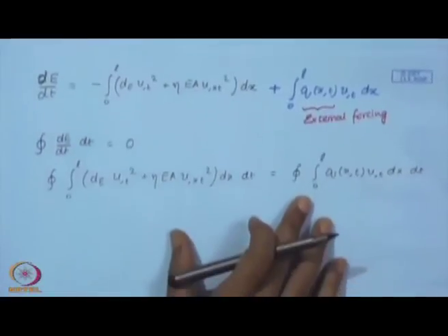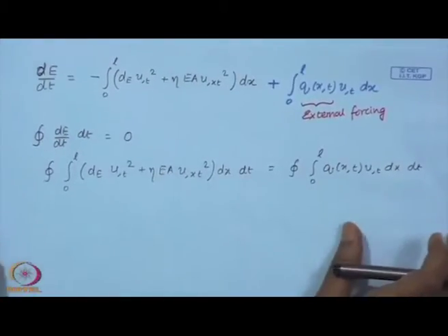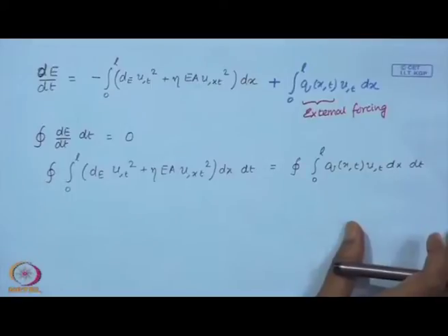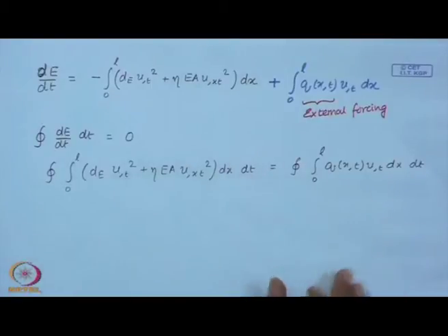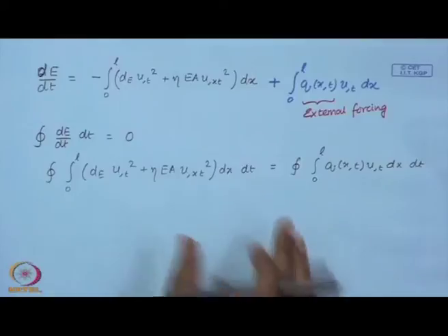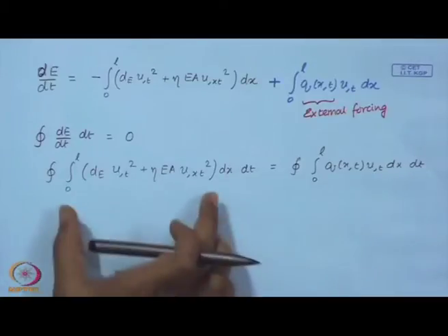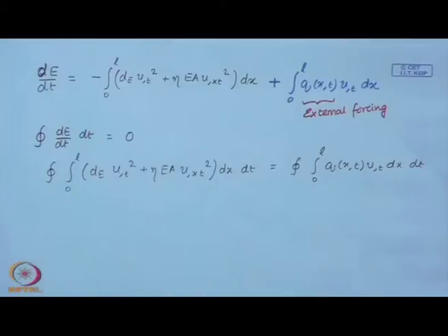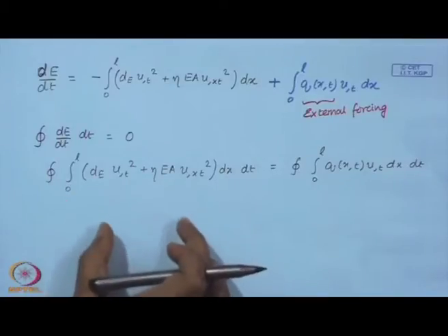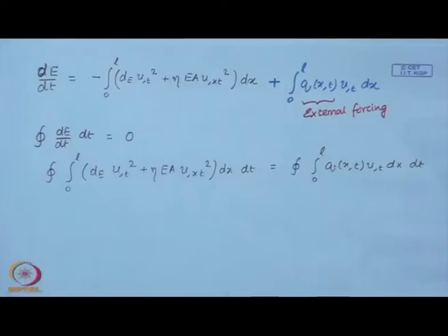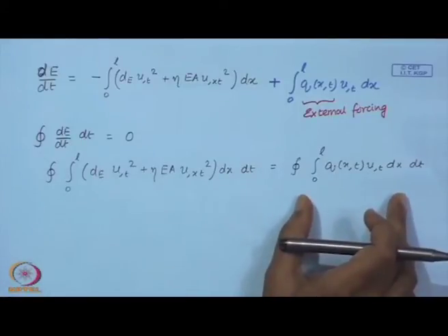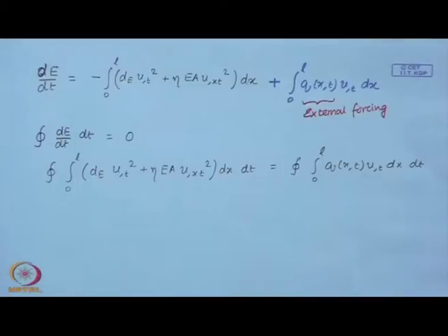So, what we have concluded is that any initial condition or any initial disturbance must die out because of these damping terms, and what remains is the steady state solution, and that can be used to estimate the energy that is dissipated, and that can be used to model the internal dissipation, as well as you can estimate the amplitude of motion in certain cases.